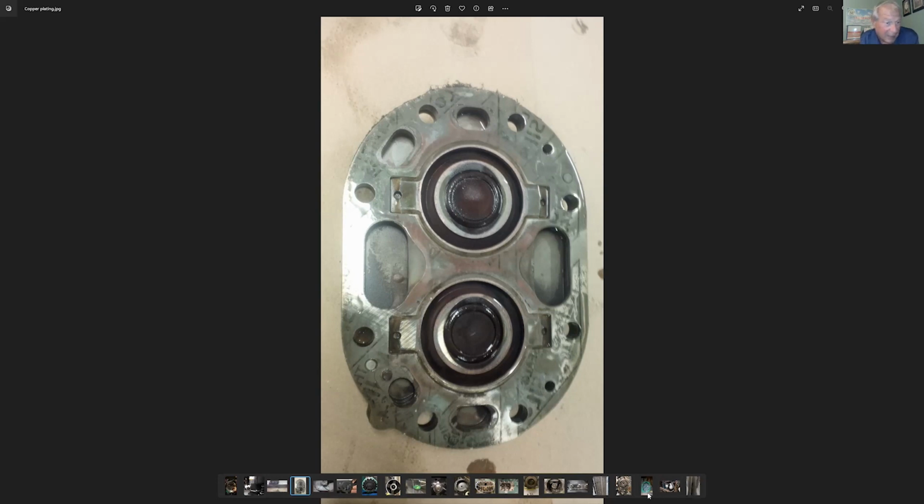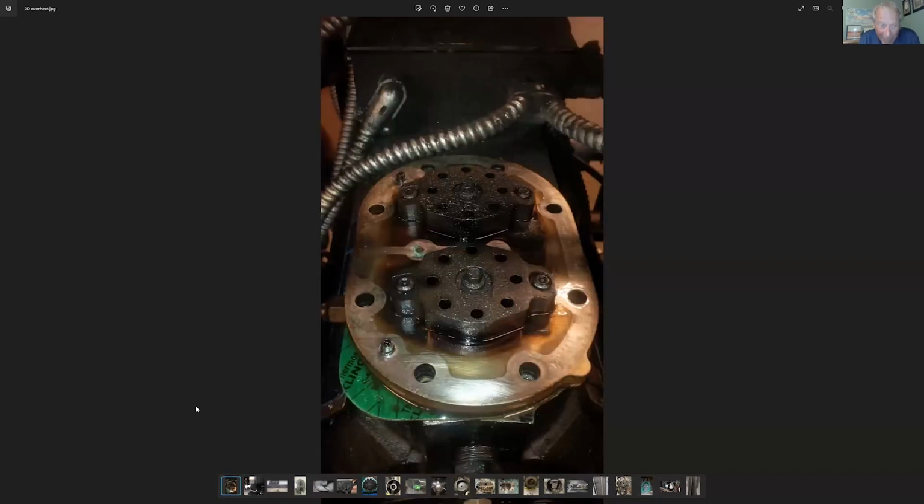Blow by is another thing we didn't really talk a lot about, but you get that wear in the cylinder wall or in the rings, and then when you go to compress the refrigerant, it pushes not just out the discharge valve, but blows back into the crankcase. Now that pressurizes your crankcase, and that can create some issues too.